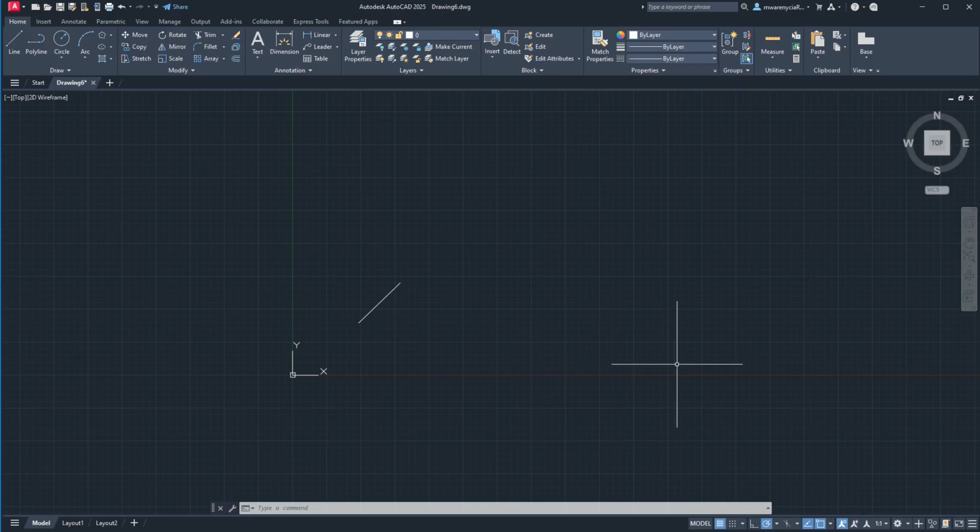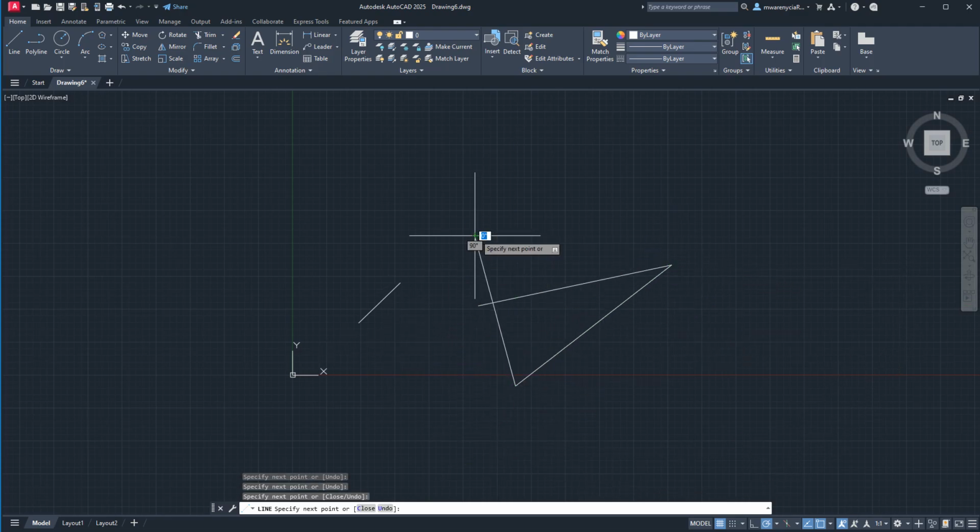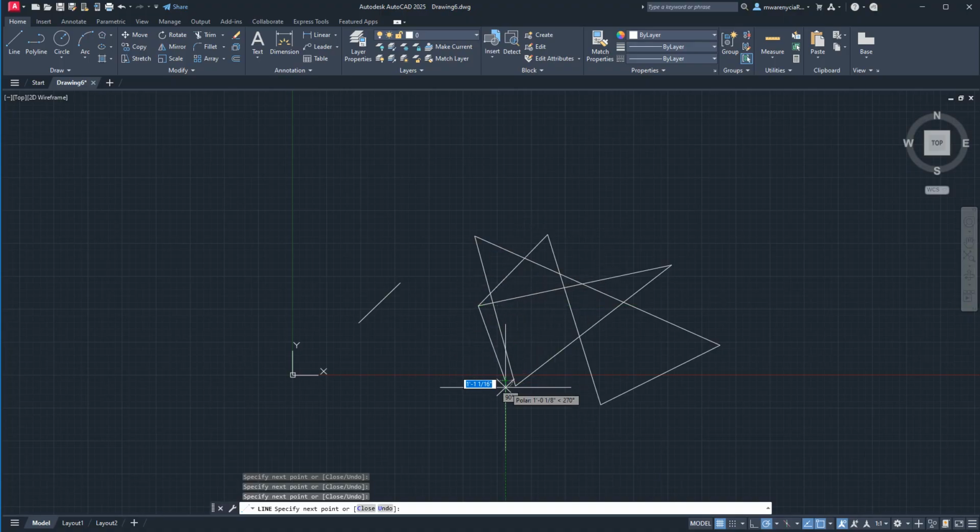All right, so I've got a line here. Let's bring up another line tool, and I'm going to hit L. Again, you can type the full L-I-N-E, or you can click on the line tool up here, but L, enter, is a pretty quick way to get this tool going. As I move around, we have a set of coordinates. The first box is X and the second one is Y, just like geometry class, right? I can manually click anywhere in here and start placing points.